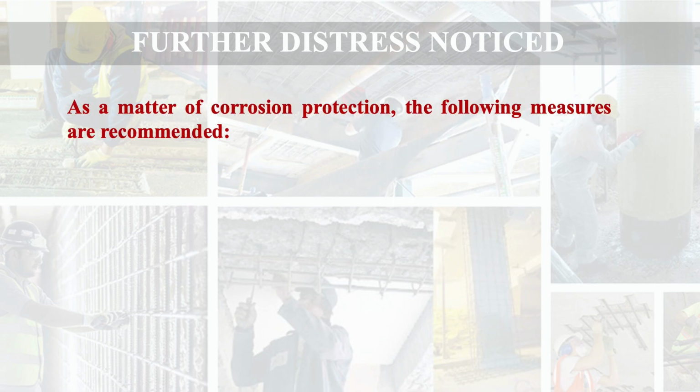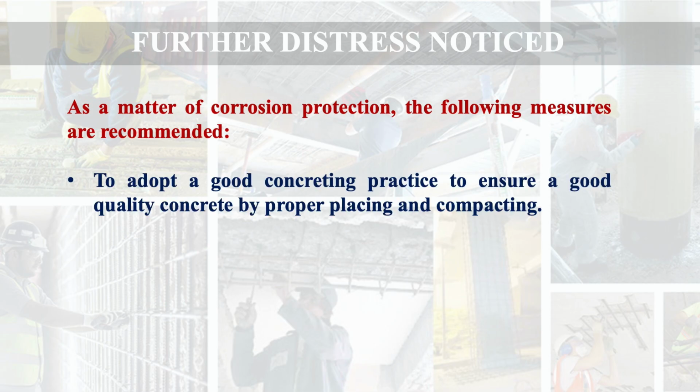As a matter of corrosion protection, the following measures are recommended. What are these measures? To adopt a good concreting practice to ensure a good quality concrete by proper placing and compacting. Because if you are able to prepare a good quality concrete which is almost impermeable, then we can ensure that corrosion will not be there.